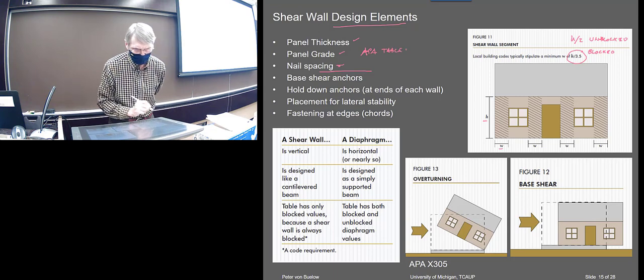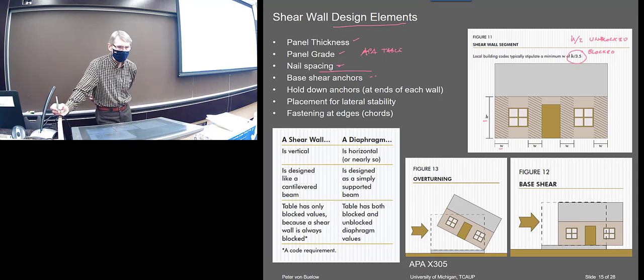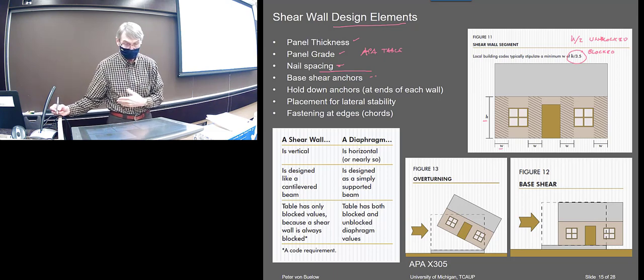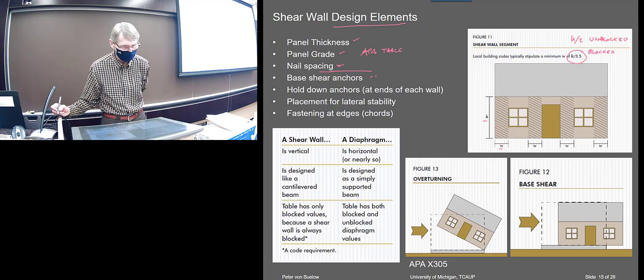Is where you get that. These base anchors, the manufacturer will give you the specification of the anchors. So this would probably be Simpson or somebody like that that manufactures the anchors. They'll give you the strength, but then you just have to follow their guidelines, and you have to calculate the force that's going to be on them, obviously, to find which ones you need.